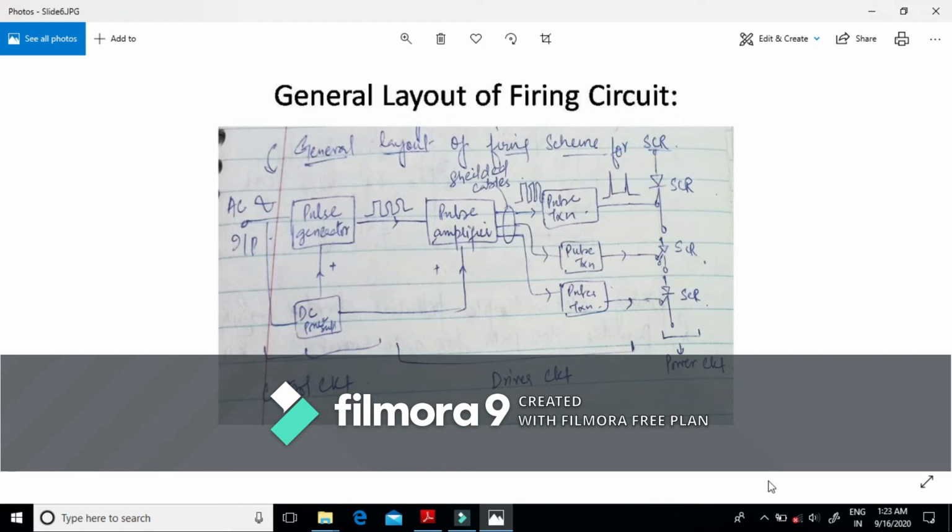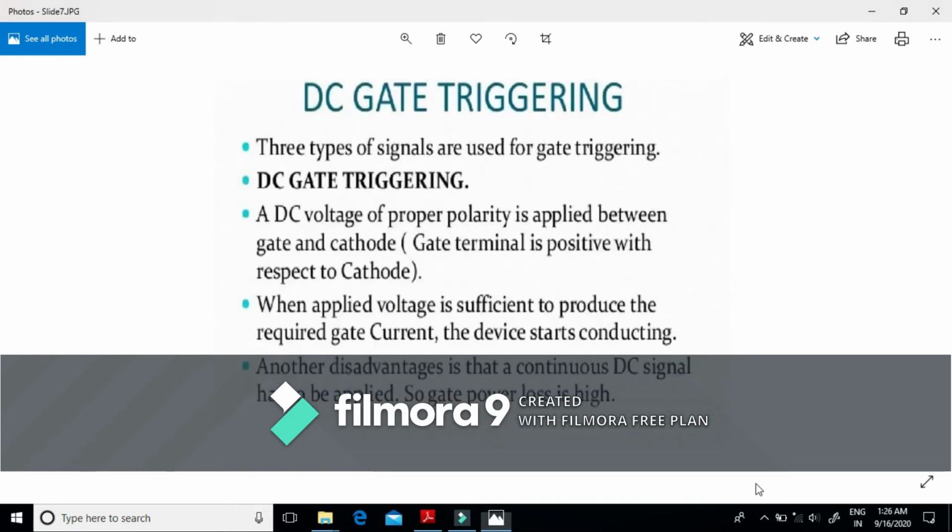And then, if we ask what is the function of this driver circuit, we can say the primary function of the driver circuit is pulse amplification, and the second primary function is electrical isolation. The secondary functions of this circuit include short circuit protection. The second point is that it provides the blanking time or the dead band during the turning on and off of SCRs.